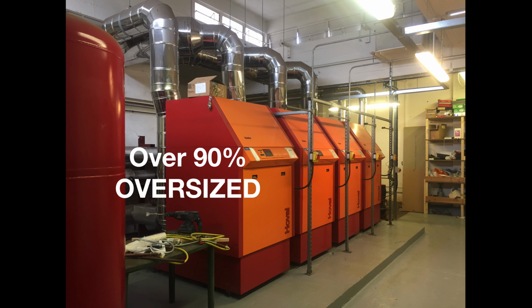Now, people talk about diversity values and all the rest of it. But what is actually needed to get boilers into their sweet spot, running at a nice low modulation rate with a nice low flow temperature, as we all now understand is required within systems, is to size systems correctly. We don't want oversizing; we'll come on to oversizing in a second.